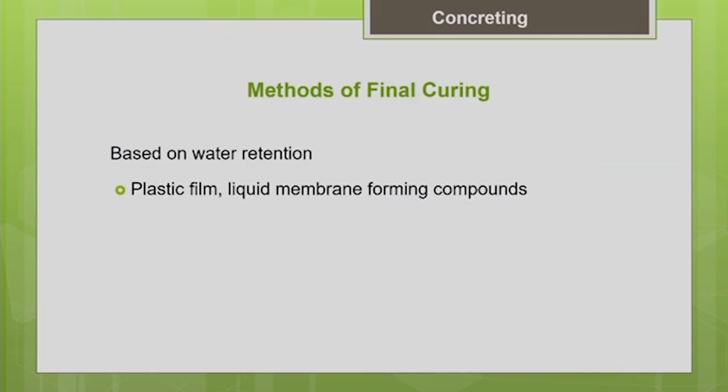So, the other method which I told you is based on water retention. Here, we do not apply water for curing, but we prevent the loss of water. So, how to prevent the loss of water? You cover the concrete surface with a plastic film or any polyethylene film, and prevent the loss of water from within to the outside environment.